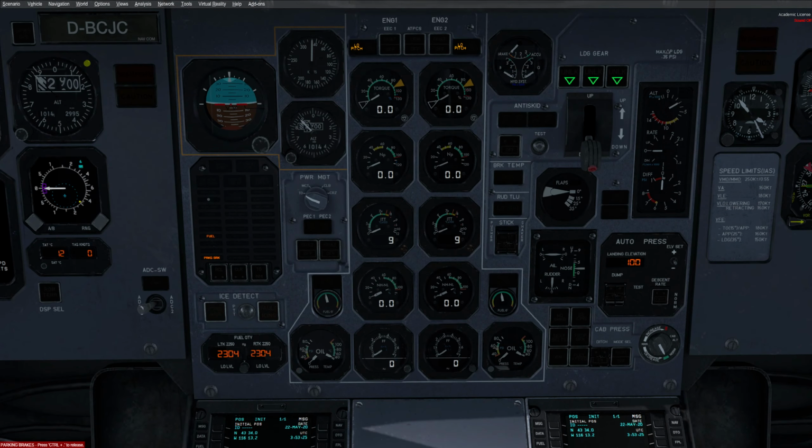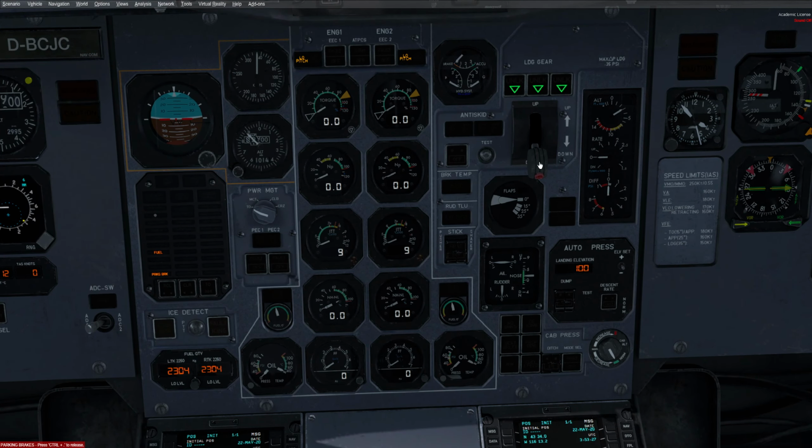Dropping down now. Looking past the gear lever, looking past the flaps, looking past the trims. This automatically knows the elevation of the departure airport up to 3,500 feet. You can change the landing airport's elevation by left clicking or right clicking. Drops it. The descent rate, leave it alone unless you're descending very rapidly at 1,500 or more a minute.